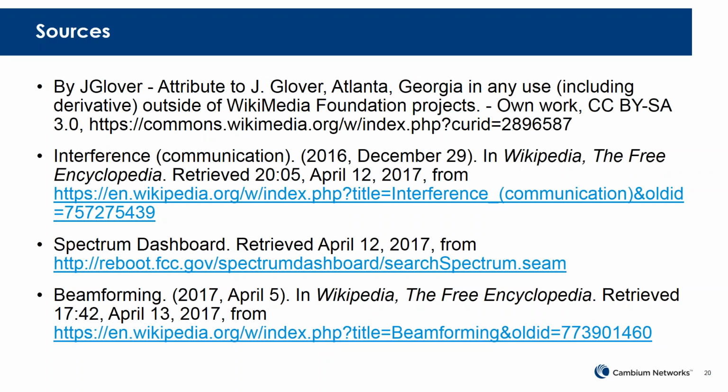I think typically for point to multipoint, the go-to is that you put a sector antenna for the access point and some kind of parabolic antenna for each of the subscribers. And I think the idea there is typically access points can be more expensive, and so you want to make sure it's got this wide range.